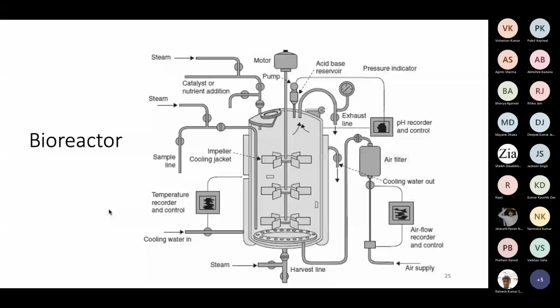And for tall reactor and very large scale production unit, we try to have the motor drive at the bottom instead of the top, because whenever you use this long motor shaft, you can see the liquid level could occupy maybe 50% to 80% of the total reactor volume.